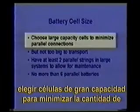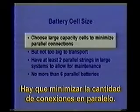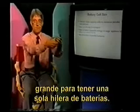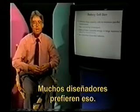In other words, you want to choose large capacity cells so that you minimize the number of batteries that you're connecting in parallel. We want to minimize the number of parallel connections. You can go to the extreme and simply choose one large battery, so you have simply one string of batteries. A lot of designers prefer that.